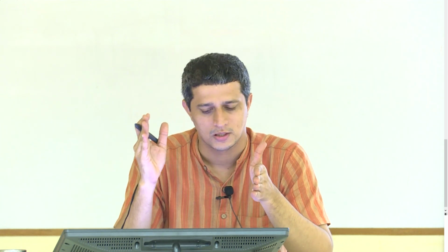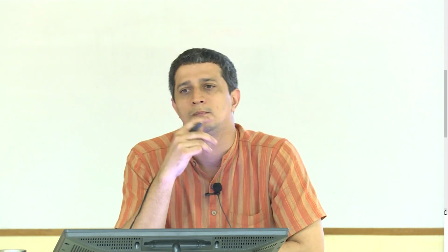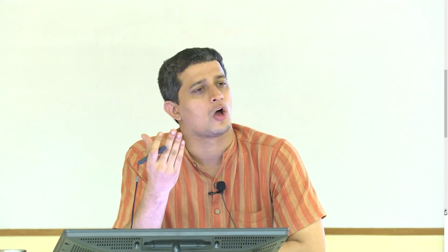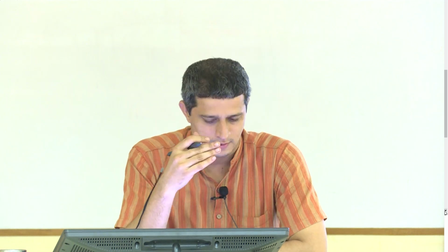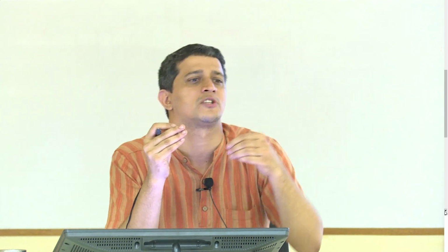Okay, so that's what I am trying to analyze here, again under these theoretical conditions, under the assumptions we have made. So if my clock edge first of all changes, let's say, and D changes after that, what is the minimum time that D needs to even arrive at the transmission gate? I1, right?